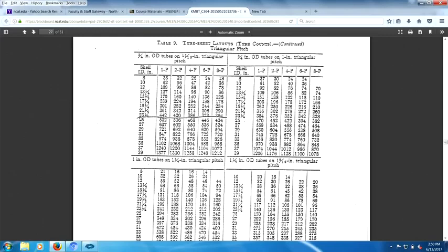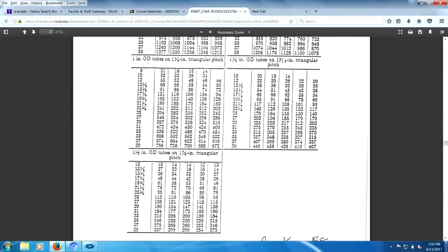And so if I have a 23-inch shell sitting here, I'm doing a one pass, right? I would have a possibility of putting in 442 tubes that are 3/4 inch. Isn't that fantastic? That's fantastic, I'll tell you.